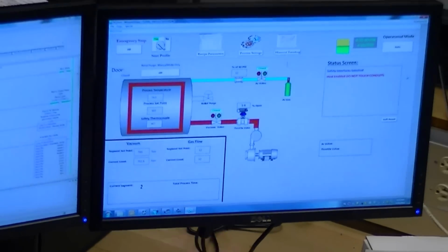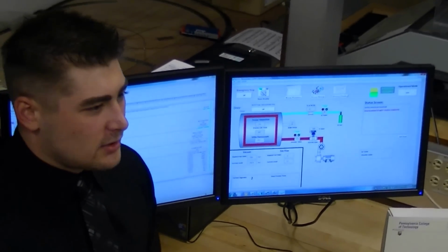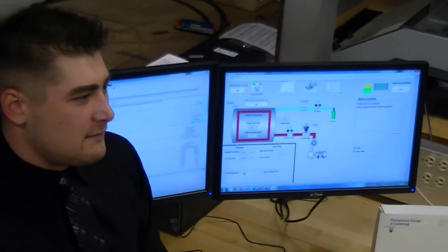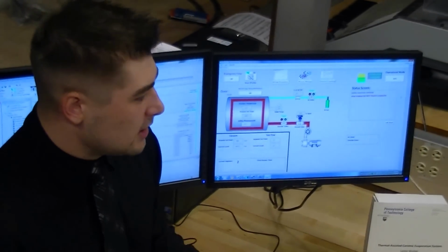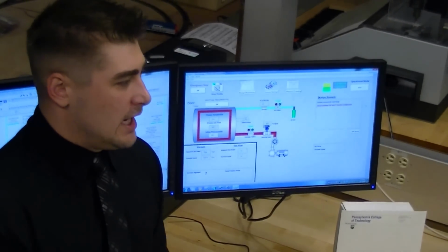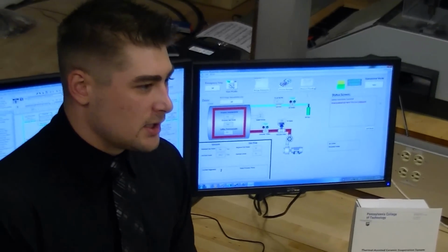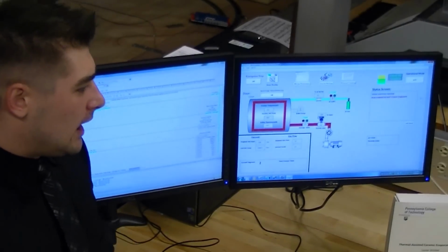And inform the user that there's been a condition met for that. I also have two sensing thermocouples, one for the process and one for safety. In the event that one thermocouple breaks from deterioration or there's a hardware problem, you don't want to just open that up if it's, you know, a very volatile temperature. So we also have that backup sensing.